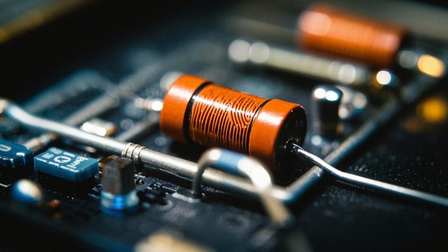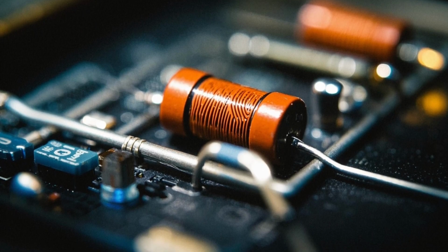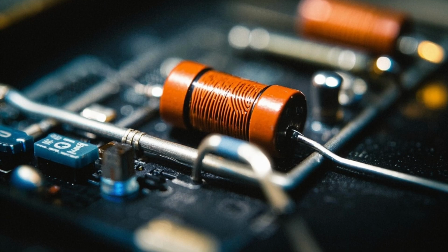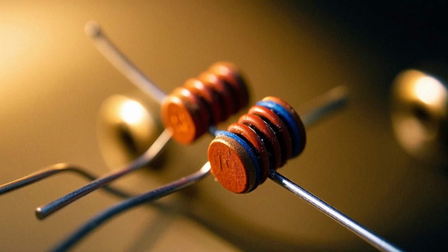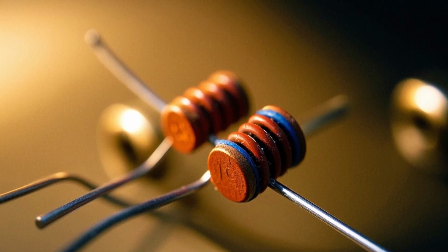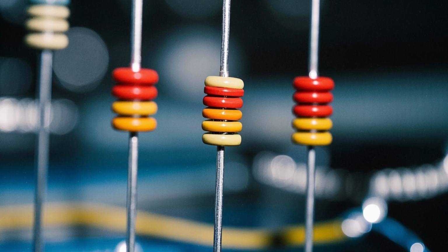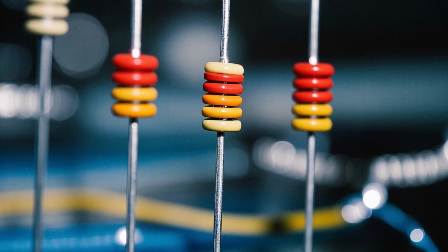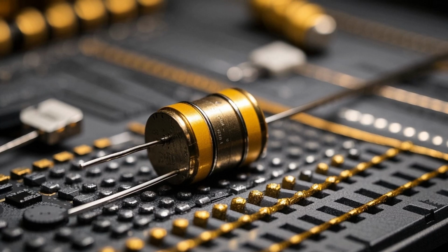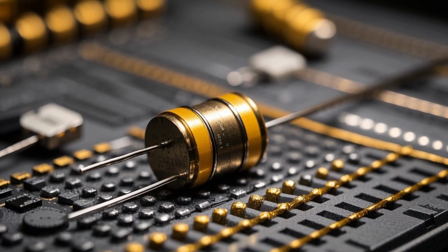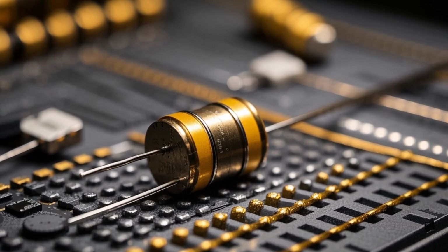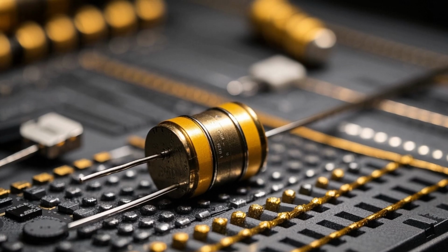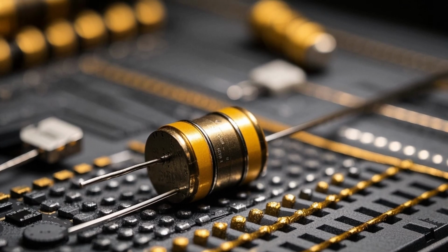Using the resistor color code, we can see that brown equals 1, black equals 0, red equals 2, so the first two colors represent the first two digits of the resistance value. And the third color, red, which is 2, represents the multiplier, which in this case is 10 to the second power. So 10 times 10 equals 100. Finally, the fourth color, gold, represents the tolerance rating of the resistor.